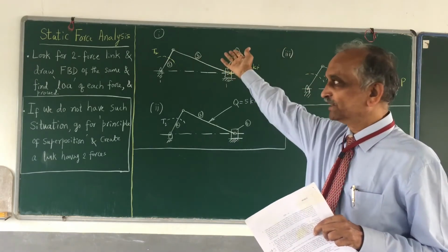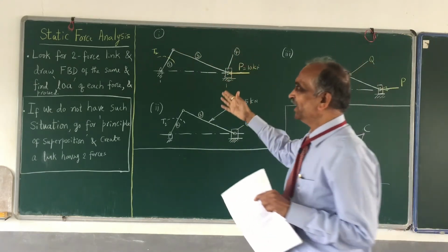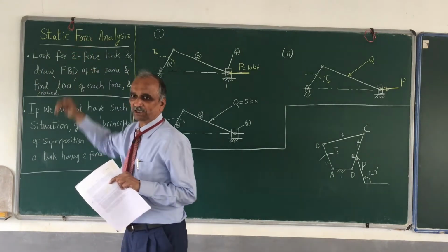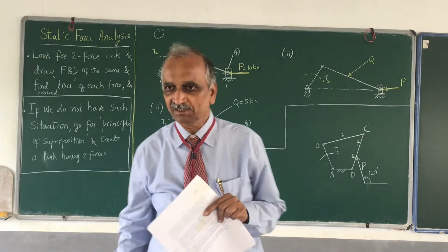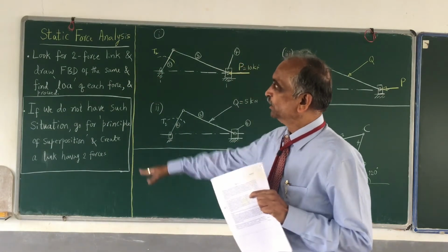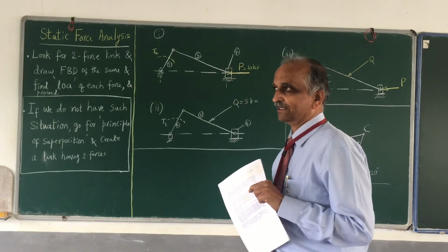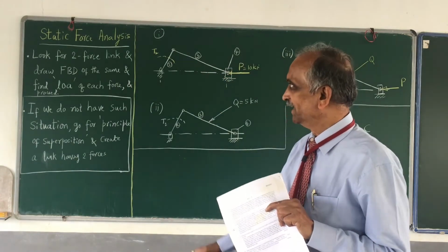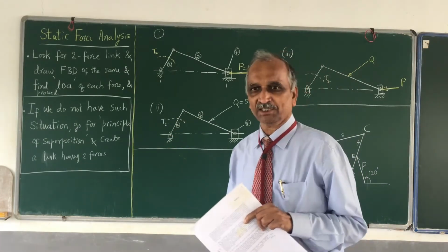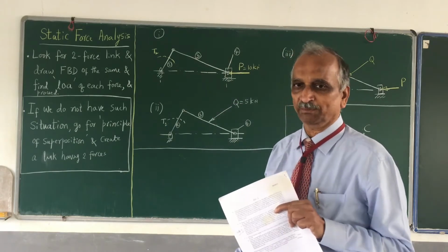For static force analysis, I shall not go into detail about what is static, etc. I have made a statement here. While solving such a problem, please go through that statement. Look for a two force link. When you start your analysis after drawing the configuration diagram, spend a couple of minutes, go through all the links, and identify the link which is a two force member.